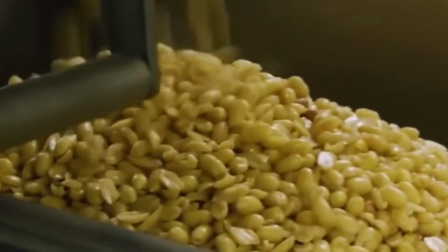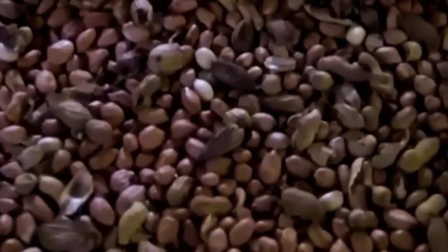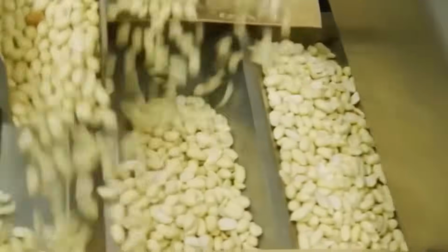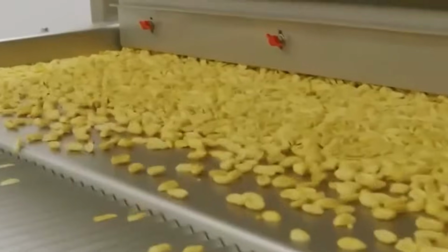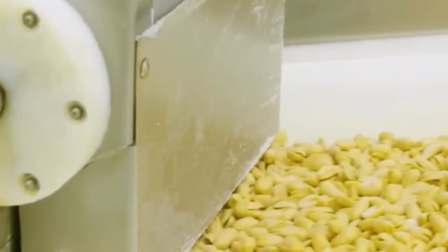The caramel is cooled rapidly using forced air and chilled roller contact to reach slicing firmness. The tri-layer slab, consisting of nougat, peanut butter, and caramel, is conveyed through a compaction system consisting of top and bottom pressure belts to eliminate internal air pockets and ensure structural uniformity. The slab then enters the slitter station, where rotary knives cut it longitudinally into lanes matching the final bar width.